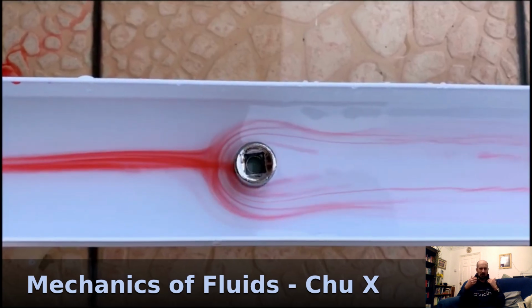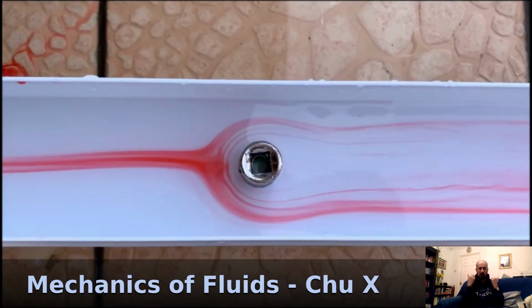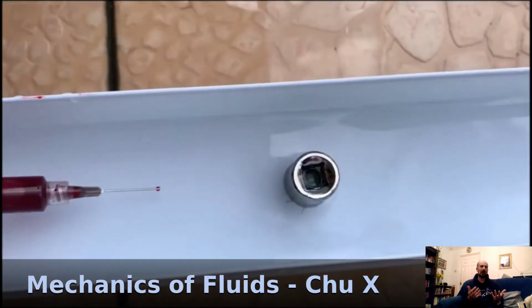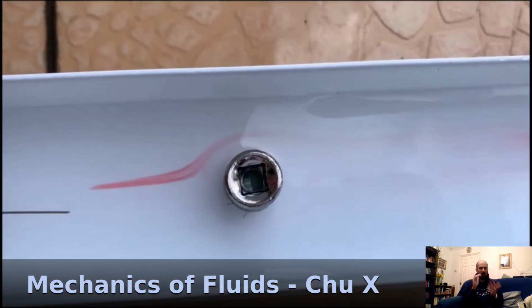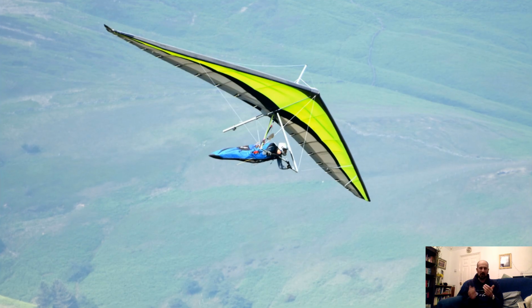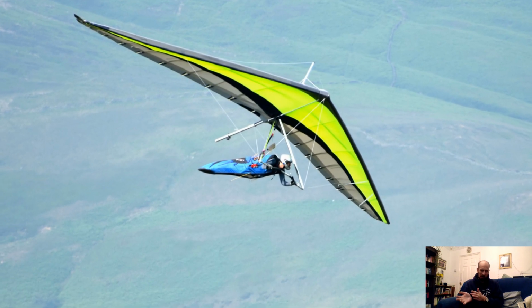So at this point I should quickly go over what we mean by induced and parasitic drag. Starting off with parasitic drag, that's the one which is relatively easy to visualise. That's just the resistance you get when you try and push anything through a fluid or through the air. That's the friction of the air flowing over the surface. It's to do with the shape of it as well.